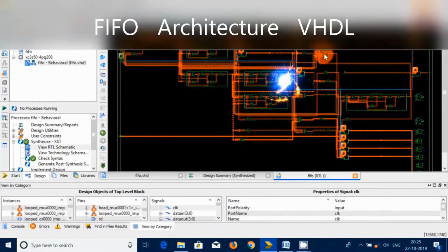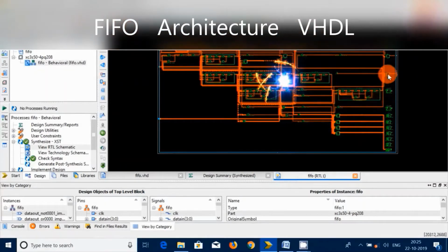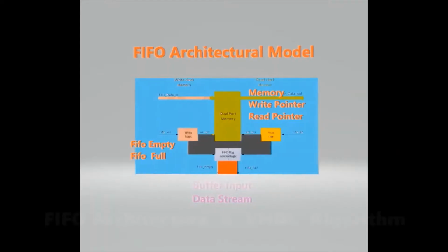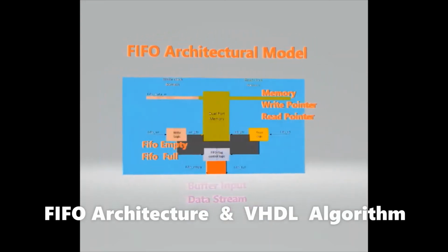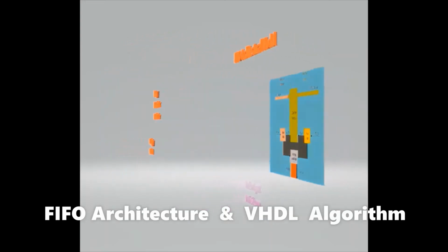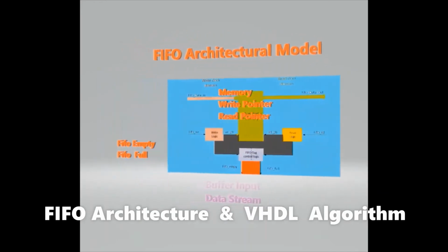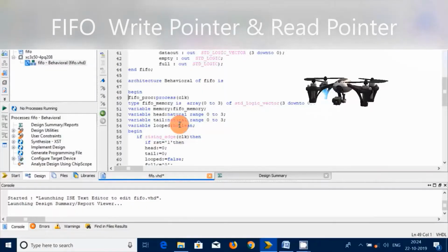The FIFO is used to buffer the minimum number of burst data in order to guarantee continuous reading from the FIFO without interruption. So in this case, the FIFO read control logic block checks for the almost empty flag going high and sets FIFO read control signals to read continuously from the FIFO.